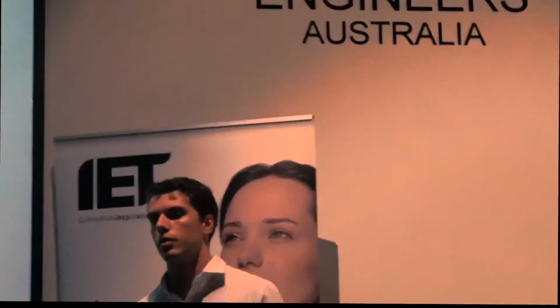Looking at damage, typical damage from hail for glass, for example, is it usually a deflection failure or a punching failure that causes a window or a large pane of glass to fail? So usually in buildings, it's deflection, but on cars, it's puncture. So the two are valid failure mechanisms, and if you were going to have a standard, you would want it to cover both, so you design for both. But you really would have to run experiments. You'd want to run experiments to validate this as well, but to actually develop a model of designing for puncture, you'd want to run experiments.